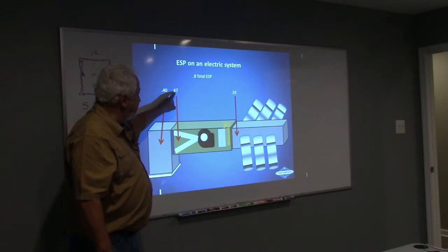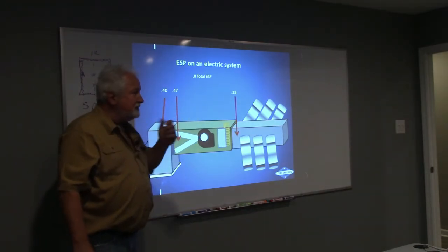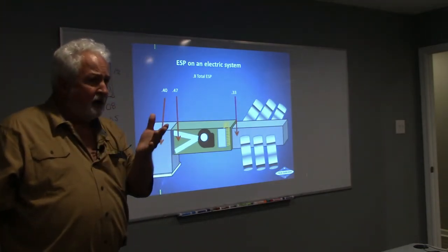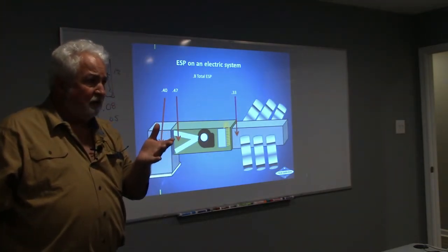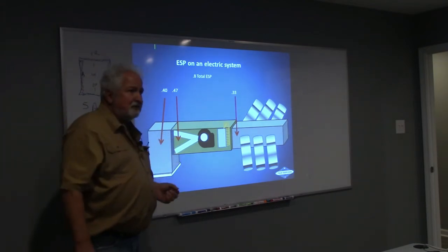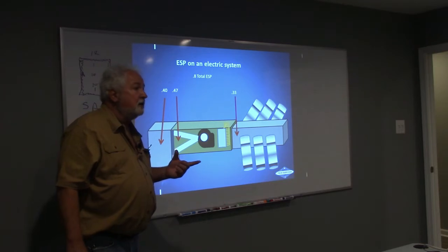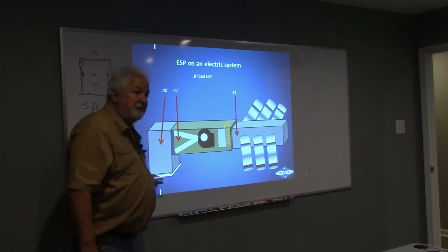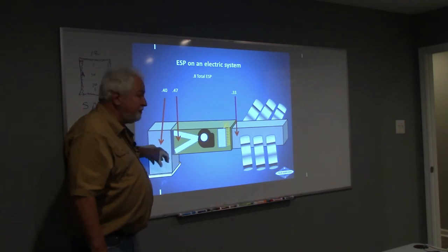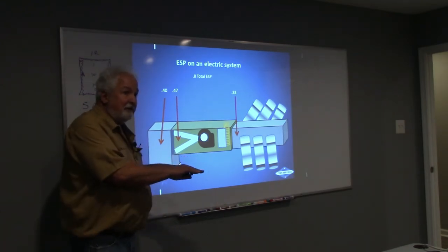But I see 0.7, and 0.33, 0.47, 0.33. What do I see about this whole total system? Returns higher, right? So the system's sucking, right? If it sucks and it's not the filter, what must it be? The return air. Size. Maybe the grill. Something's undersized there. Or maybe it's going up through a chase and half the chase is dinged off inside there.